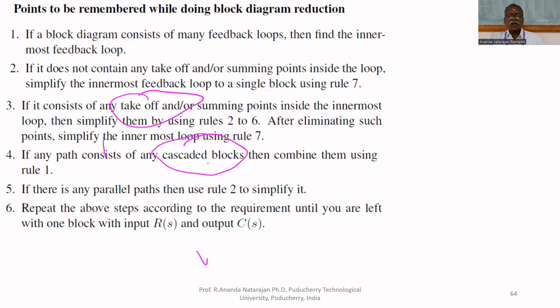That's all. If the path consists of any cascaded blocks, combine them using rule 1. If they have parallel paths, add together, second rule. Repeat the above steps. Algorithm: repeat the above steps from 3 to 6 continuously. You will get a single block diagram.